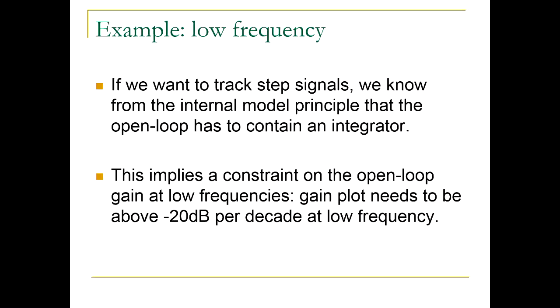What we learned already from Laplace transforms and the internal model principle is that if you want to have zero steady state error for step reference signals, your open loop transfer function has to contain an integrator.